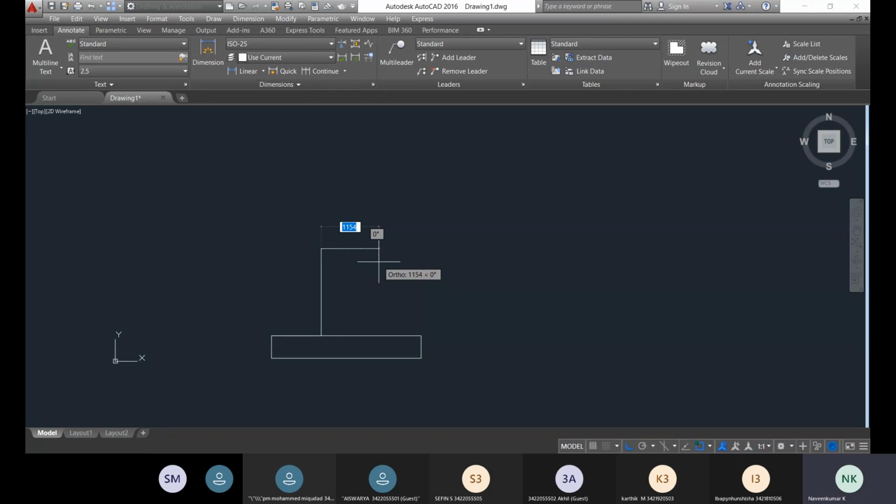extended, what is the meaning is, up to this the reinforcement detailing is different. From this point to the upper point, the reinforcement detailing is different. Why is it happening? Distribution only. If the load distribution is more, you need more percentage of steel. So at the top there will be more percentage of steel, and at the bottom there may be reduced percentage of steel. Okay, so that is the thing.